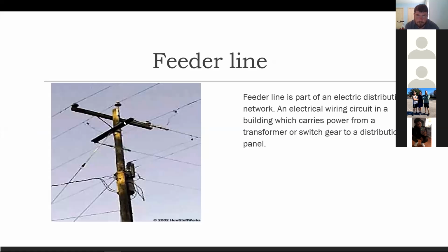So it's coming off. We'll talk about this for just a moment. Your voltages and your priorities are going to start from top to bottom. So this is my feeder circuit on top, my tap on the bottom, which is actually, is this a fused or a solid tap? That looks solid. There's no fuse there, right? Then I've got a transformer here.